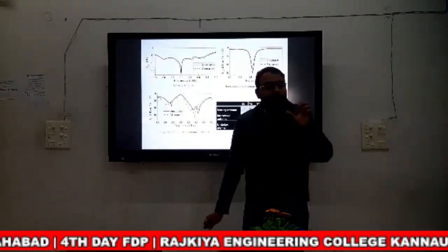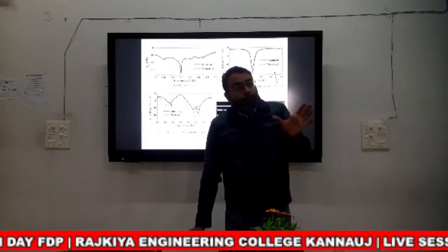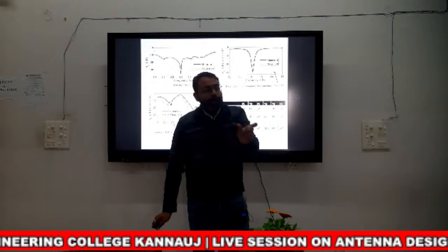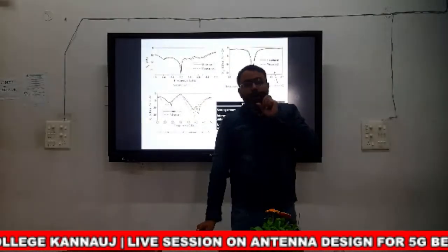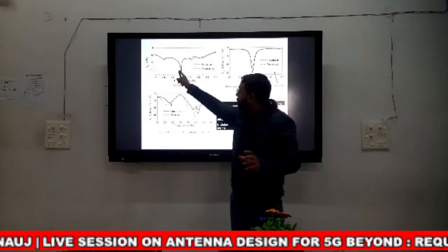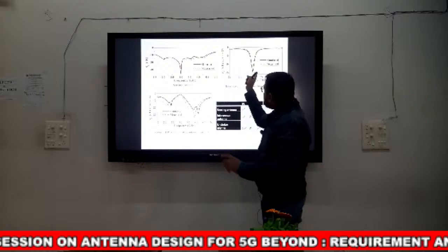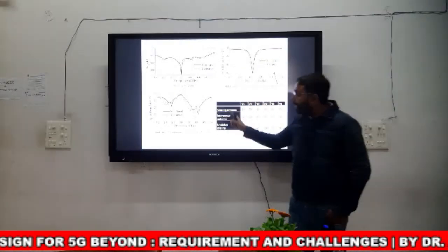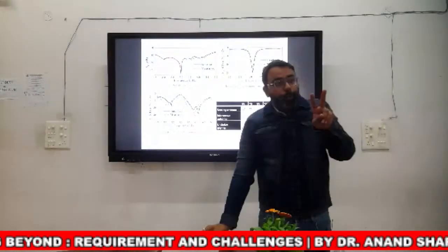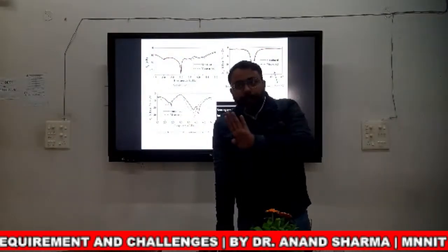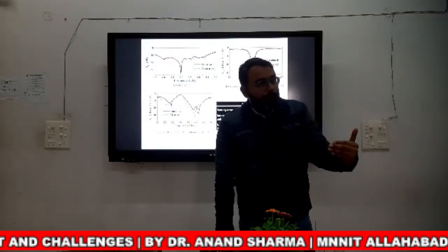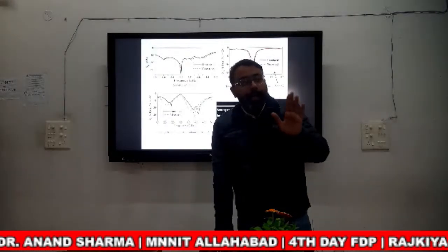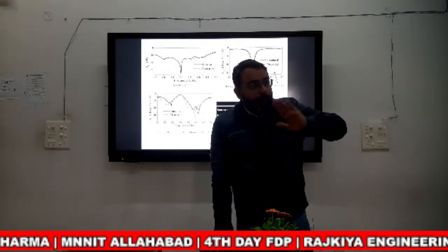Because in case of interweave, first we have to identify which part of the spectrum is idle. So first you identify with the help of the sensing antenna, and then start transmission on that frequency range. In case of underlay, both primary user and secondary user communicate at the same time until and unless the secondary user starts any interference with the primary user communication.